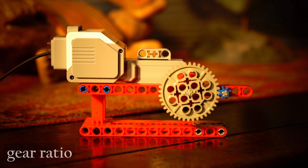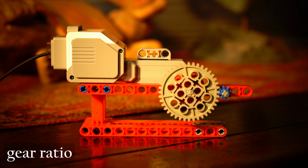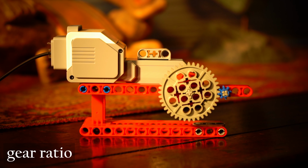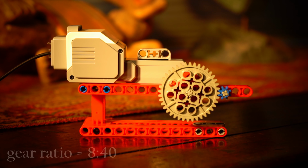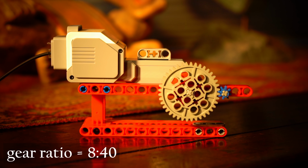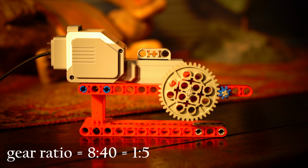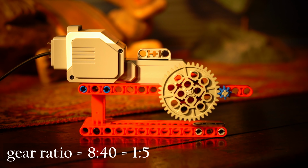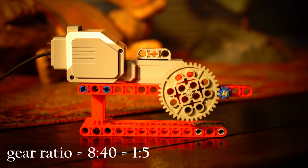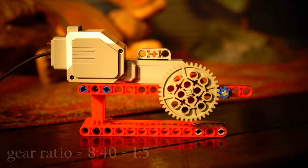Gear ratio is the ratio of the number of teeth on the driven gear to the number of teeth on the driver gear. It can also be calculated as the ratio of the diameter of the driven gear to the diameter of the driver gear. In this simple gear train, a 40-tooth driver gear powers an 8-tooth driven gear, so the gear ratio is 8:40, which reduces to 1:5. In other words, the 8-tooth gear will make 5 revolutions, while the 40-tooth gear makes only 1, so the small gear will be turning 5 times faster than the larger gear.